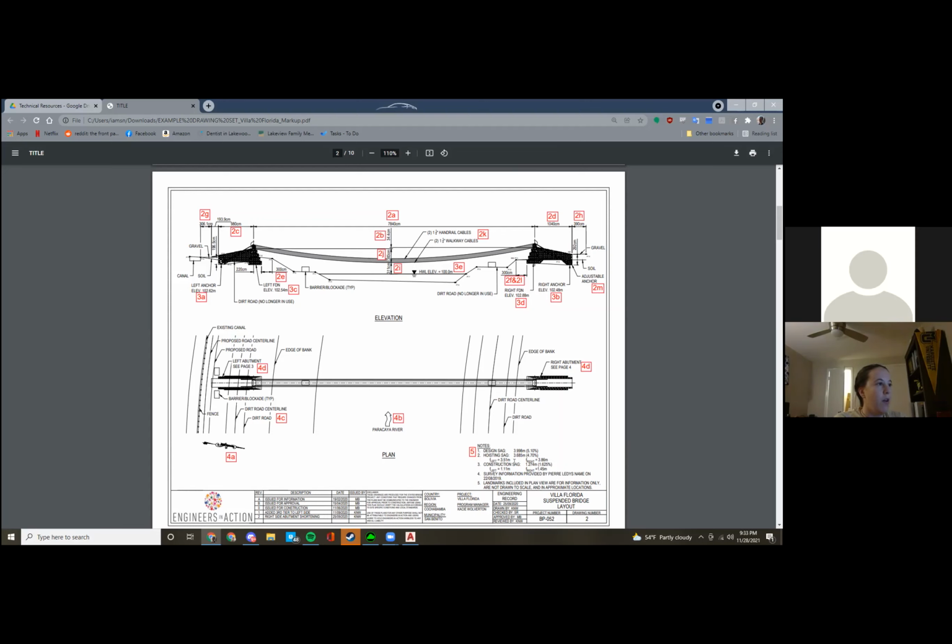So I put my sag value, the percentage that I've calculated, and what the measurements are for the saddles, from the left and right. And then, as we've done before, hoisting sag is here. So my 4.7% of the sag for this particular design, and then my F values from the left and right towers.